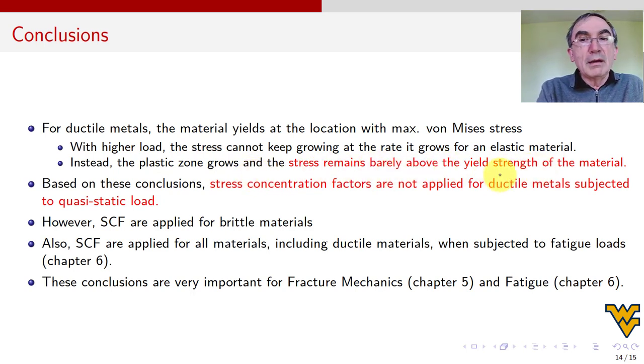You see, barely, okay? So based on this conclusion, stress concentration factors are not applied for ductile metal subject to quasi-static load. This is a big if, because if it's fatigue, yes. So stress concentration factors are applied to brittle material, because they don't yield, so they have to take all the stress with the stress concentration factor fully applied. But the other thing is stress concentration factors are applied for all material, including ductile, when subject to fatigue loads.